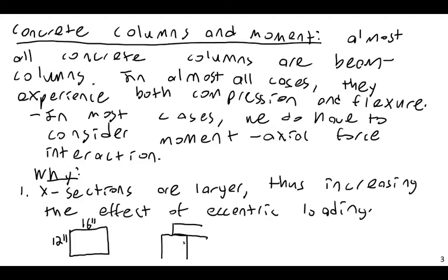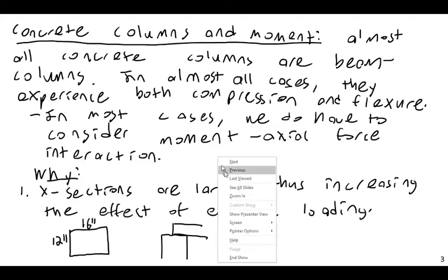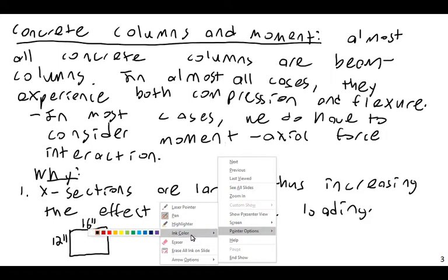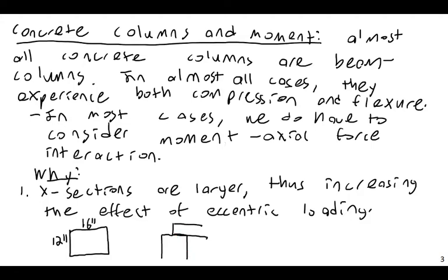But look at this diagram here. Where is the center, how is the force actually being transferred down into that column from the beam? If we treated this just as a naive pin connection, ignoring the actual rebar development lengths and things like that, at that connection, this is going to be distributing force and stress down like this. There'll be an area here. But where is the centroid of that force? The centroid of that force is actually right here. In this particular diagram, as I've drawn it, the centroid of the force would be about there.